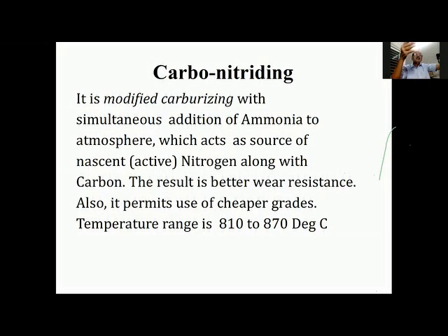And it is sufficiently good because the peripheral speeds are also lower, so wear resistance is not an issue. So those gears are invariably carburized, whereas if you go for two-wheeler or four-wheeler, the peripheral velocities are higher, and the requirement of torque transmission is relatively lower. So you can afford to have a shallow case and therefore go for carbonitriding.